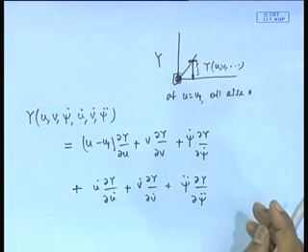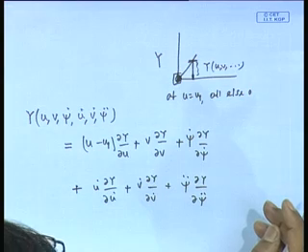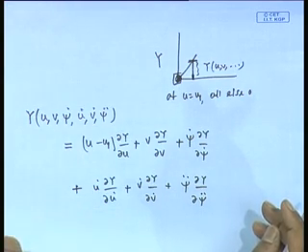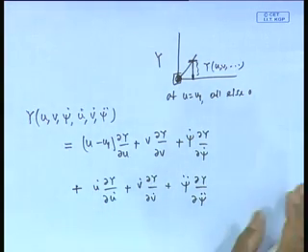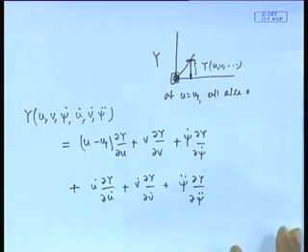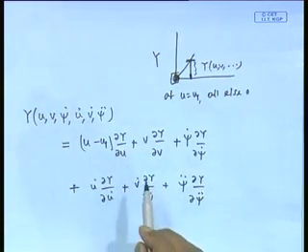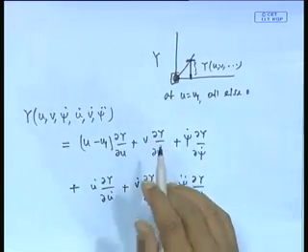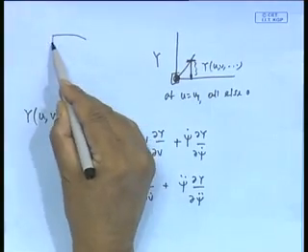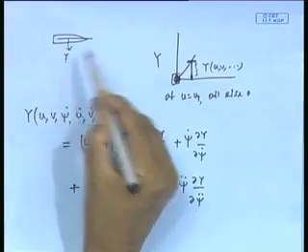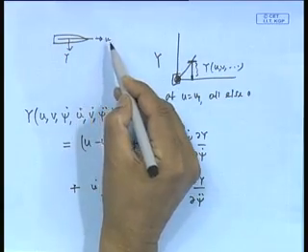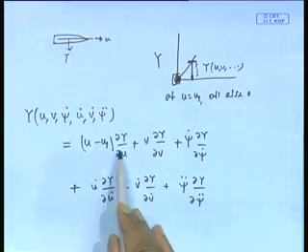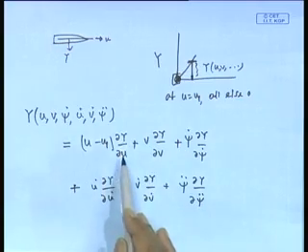Okay. This we agree. Now there is more to it. Now we will see still some picture. What is dY by dU? Essentially variation of Y against U. How much is Y changing? How much is the sway force, the Y force? See here, this is my Y force. I want to find out if I change U, make changes here, dY by dU is the change of Y with respect to U.